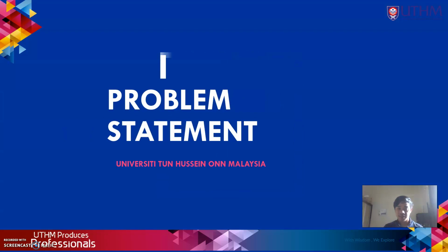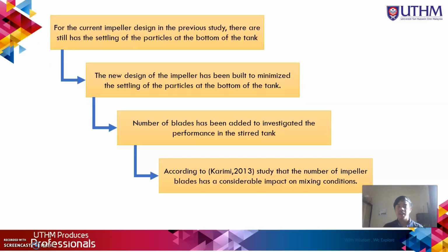For the problem statement, for the current impeller design in the previous study, there is still settling of the particle at the bottom of the tank. The new design of the impeller has been built to minimize the settling of the particle at the bottom of the tank. Number of blades has been added to investigate the performance in the steel tank. According to Karimi 2013, the number of impeller blades has a considerable impact on the mixing condition.